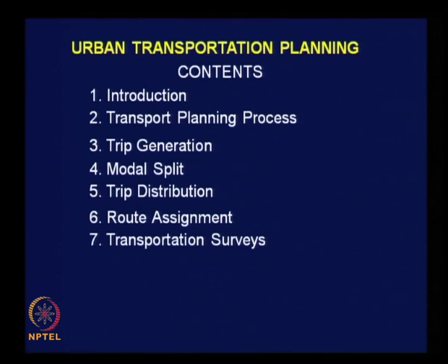Once we have clear understanding of the factors that influence trip generation, mode choice, trip distribution and route assignment, we know what we want. We want data related to all these factors. Once we know the requirement, then we will clearly understand how to go about collecting this information in the field. That is why I wanted to have this particular topic after the completion of the 4 steps of analysis in this course. It is nothing but collection of information regarding travel pattern, land use pattern, socio-economic characteristics and so on. That is what we will be discussing under this particular topic.